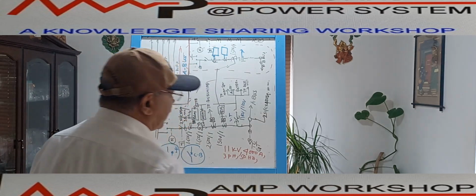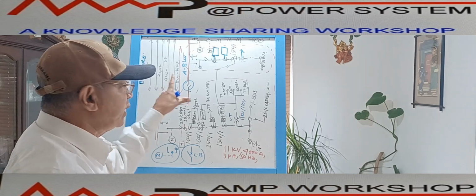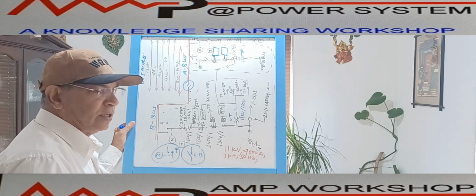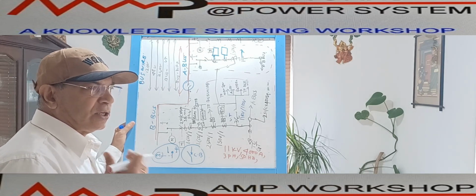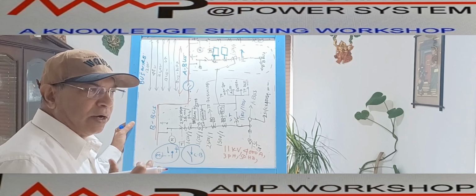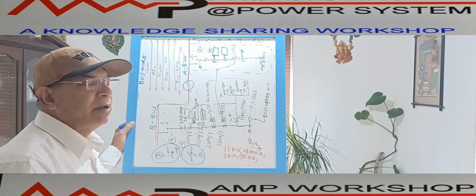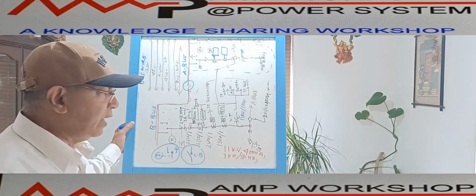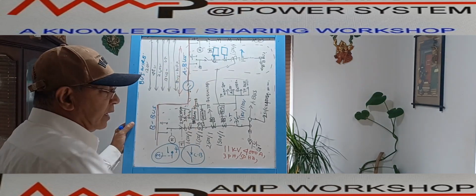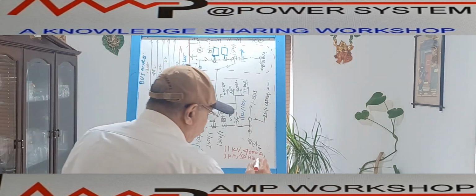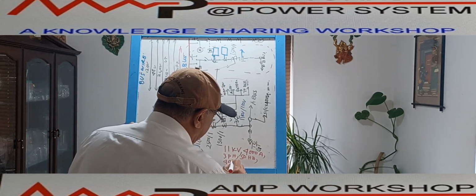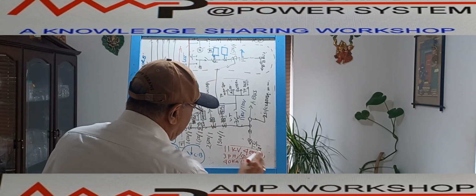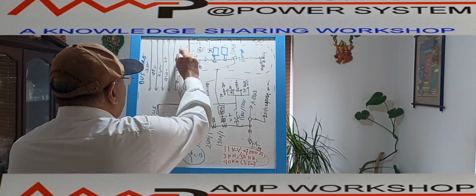And then we have to write down one important thing, the switchgear short circuit capacity. We have already discussed during our short circuit calculation, any equipment's short circuit rating has two parts: one is a current rating, another is a time rating. Suppose for this switchgear the short time rating is 3 seconds and the short time withstand current capacity is 40 kiloampere. So we'll write down here 40 kiloampere within bracket 3 seconds. This total thing will be written over here along the bus bar.